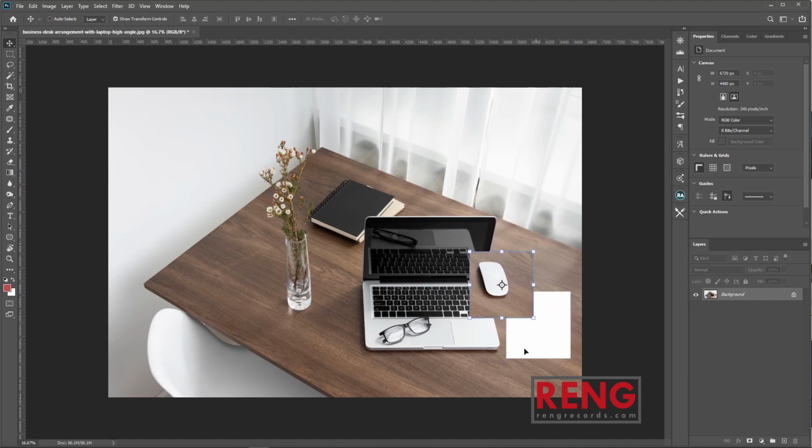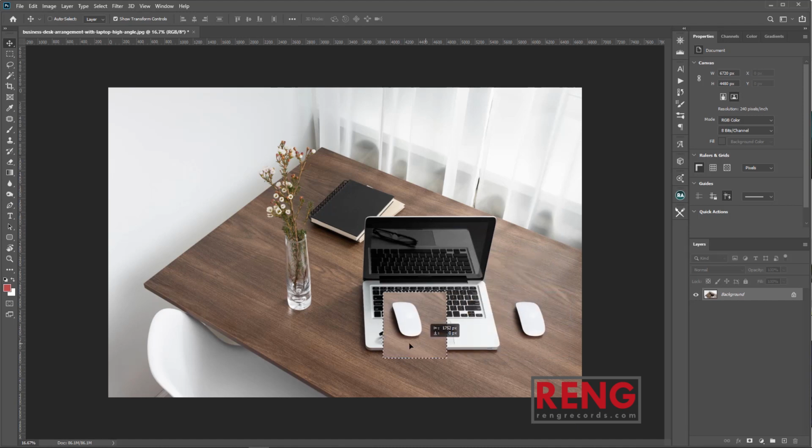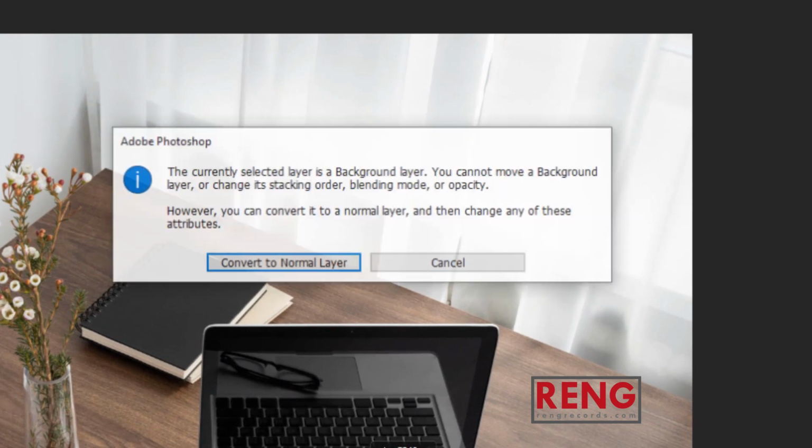When moving a part of the image, the background color will take the place of the transferred area. If you hold down the Alt key while moving, the selected area will be copied to another place. If another layer is active and you select an area that is not on that layer, the following message will appear during transfer or copy.